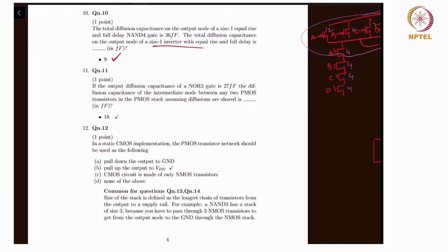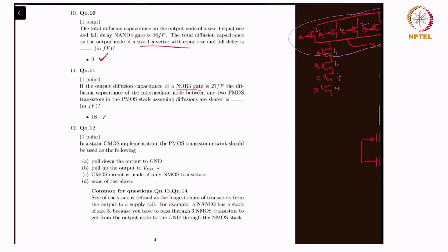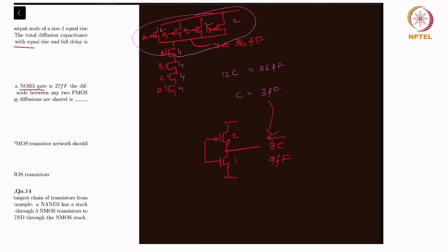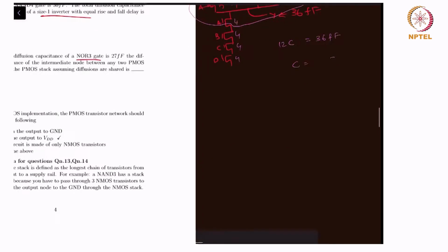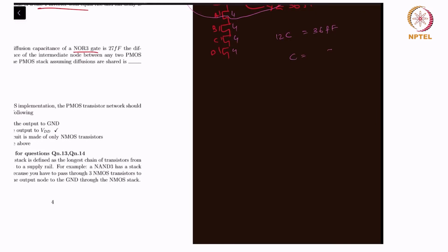And it's the same way for the NOR gate. You go to the NOR gate and you find out its capacitance, right? So for the NOR gate, I'll just draw the output nodes, right? So it's 1, 2, and 3. This is the N stack, and I'll only draw 1 on the PMOS, but you should remember that that's a 3 stack.